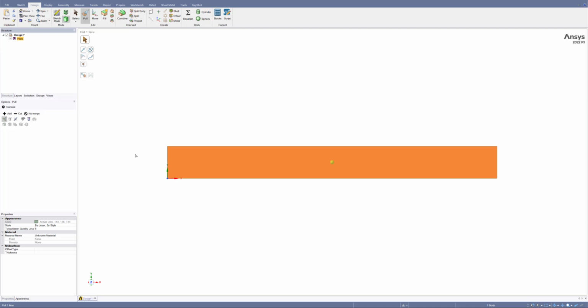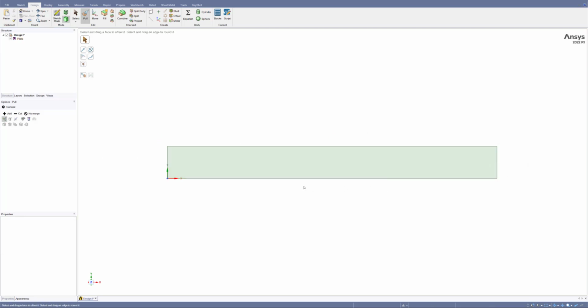But before exporting to Ansys Meshing, you can specify the boundary conditions, at least the name of these boundary conditions. To do so, you should go to the Groups tab here, click here, then you can just simply exit from the Pull tool, because you have created a surface.